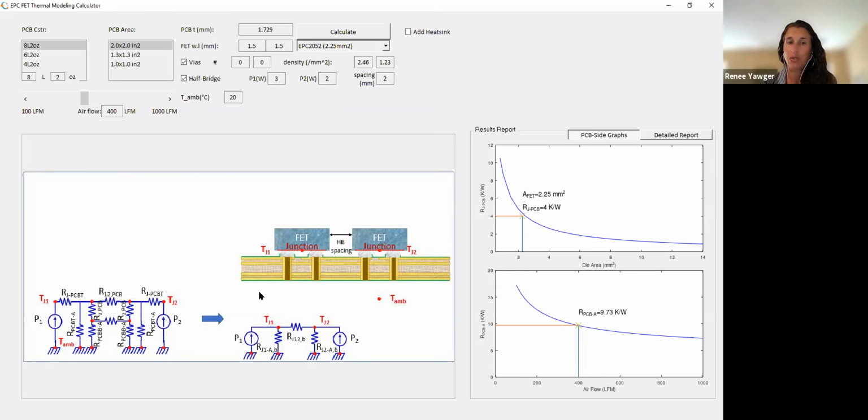Do you know which thermal camera we recommend for measuring our GaN FETs? We've used a lot of the FLIR cameras. I think that's the biggest name, and one we use. There are different accuracies of those. You don't necessarily need real high resolution. It's good if you have a field of view where you can put it down closer to the board. The GaN FETs are small.